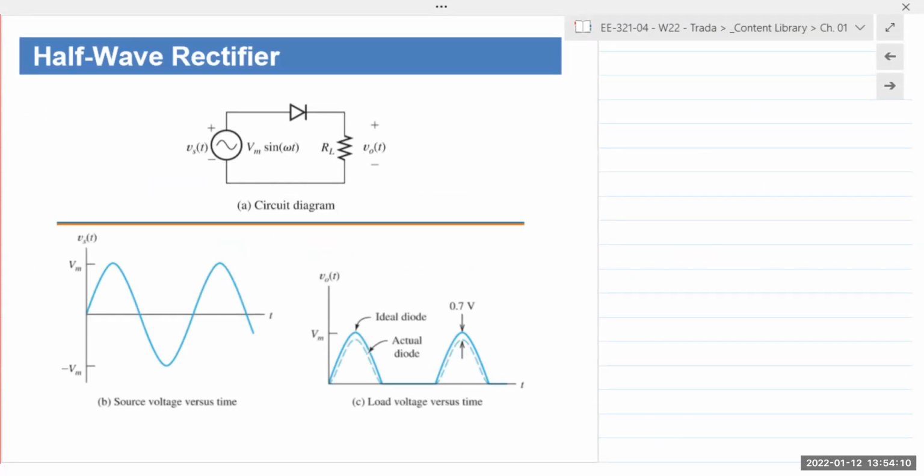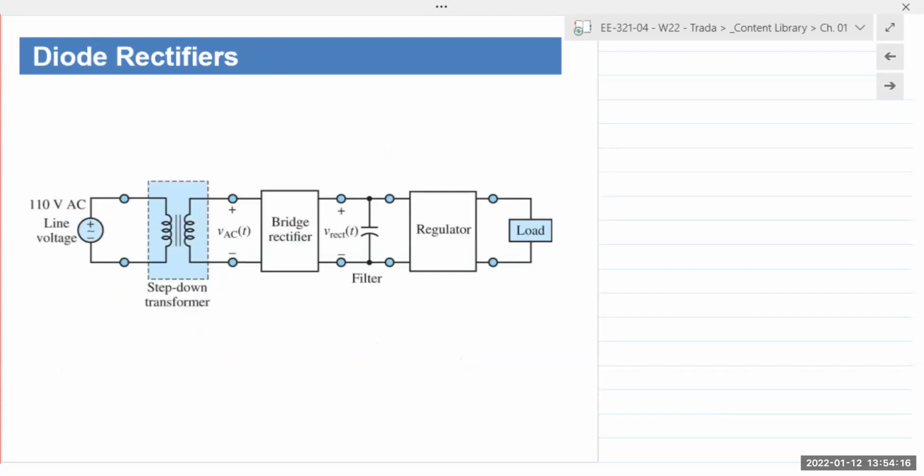So, what am I going to show? Oh, yes. Thank you. So right here, bridge rectifier. That's the one. The property that we're going to use is the one-way street property of the diode, right? Positive half cycle, it works. Negative, it doesn't. So it's only positive. And that's where most of the magic happens. The rest of it is to give you as close to a flat line as possible.